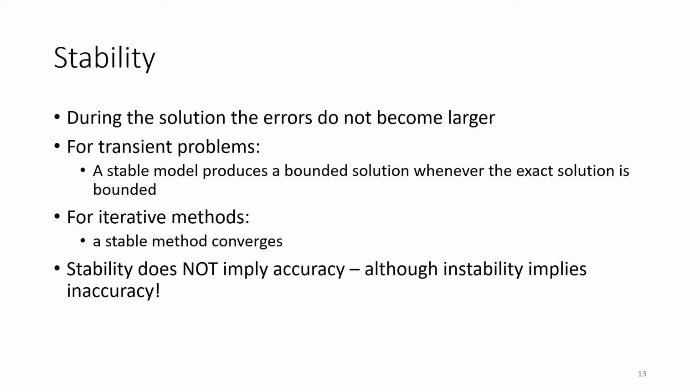You can use an implicit time discretization, which means it is stable by definition. But still, if the time step is very large, your model results can still be very, very inaccurate, because there are things coming in there, depending, as I said, on the size of your time step, which is controlled by your spatial resolution, by the physical process you're looking at, by your linearization scheme. Those factors influence the accuracy of your scheme, and that's not just stability. Stability is a part of it, but it's not accuracy by itself.